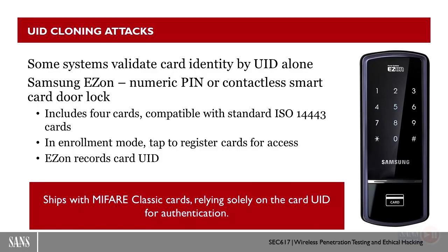They are using HF style MyFair cards, much like they would have used low frequency cards. It spits out a unique number on a low frequency card. Great, that unique number, that's in our system. You can come in. Read the MyFair card. Oh, it has the unique identifier for sector 0, block 0, unique per card. Oh, that's in our database. You can come in. So they didn't do any of the crypto. They didn't do any of the authentication. They merely chose to read the UID for a unique number per card. So that's a particular implementation failure in the Samsung stuff.